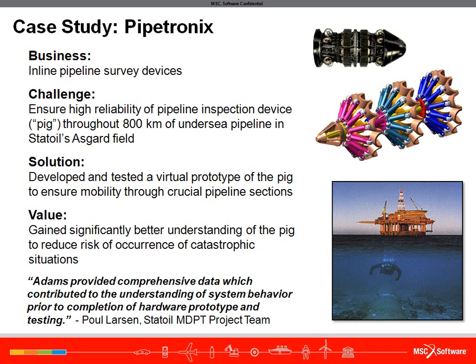Typically, data is logged and stored using onboard recording systems. Failure of a pig is defined as when the pig gets stuck in the pipeline. Retrieval of a stuck pig may involve extensive undersea rescue missions, which may cost millions of dollars. It is disappointing but not critical if a pig traverses the pipeline but does not record data. Therefore, pigs must be designed so that they successfully exit the pipeline in all possible situations.